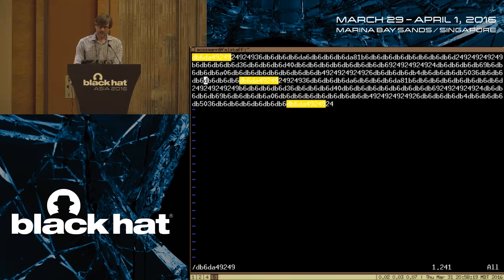Now, how far into this? If I look at my counter at the bottom right, 250 characters in, I get a repetition. And then the next one here is at 499 characters in. So I have a consistent repetition every 249 characters. So I'm seeing that what YARD Stick One is detecting as one packet is really multiple repeated packets.